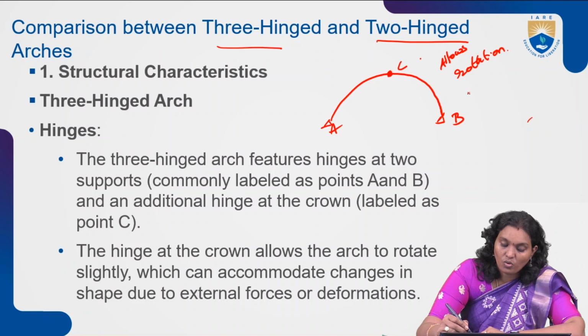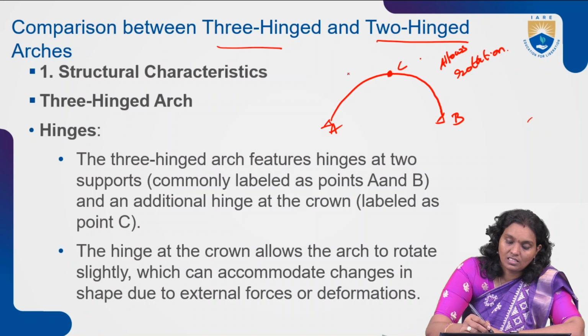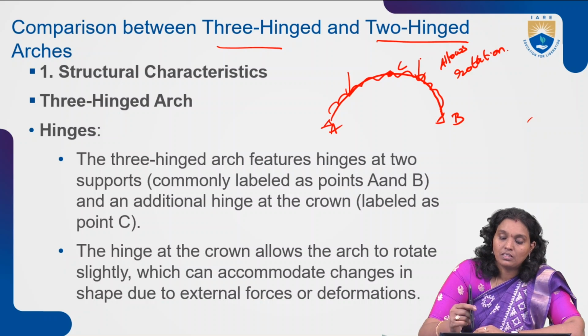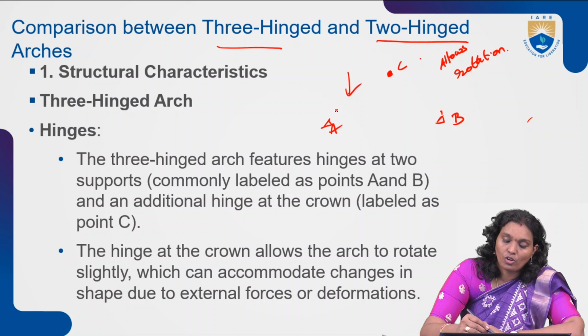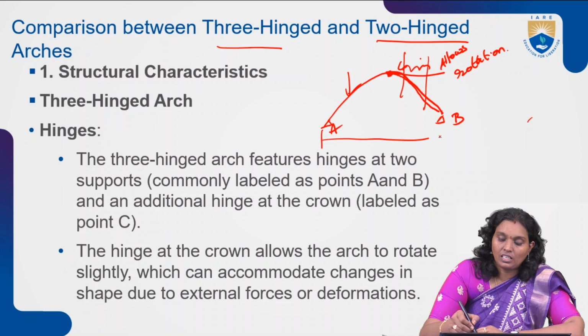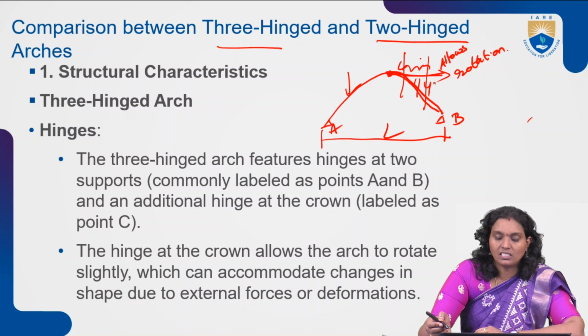So as per that, due to the external forces, whether point loads, concentrated loads or uniformly distributed load, our entire parabolic arch may deform under these loads. Otherwise, sometimes the uniformly distributed load is confined to half the portion or somewhere else, some distance only. Such scenarios we may also observe. So this is the overall span length, that is L, and only over L by 4 distance from the crown to the right-hand side of the arch, this uniformly distributed load may act.